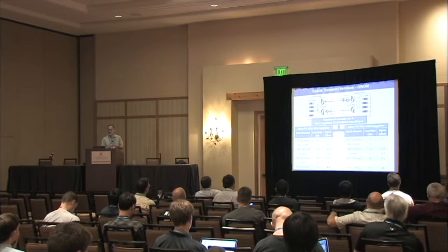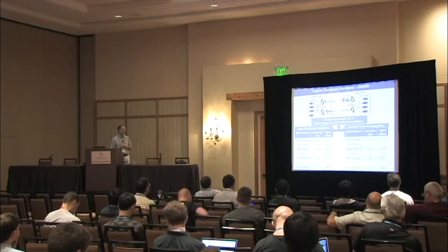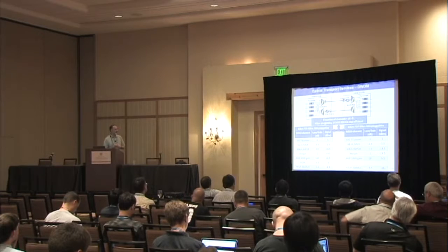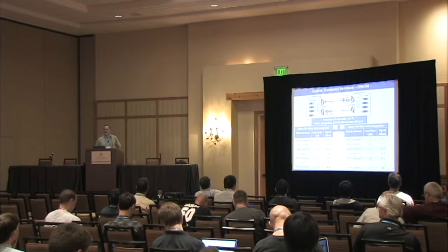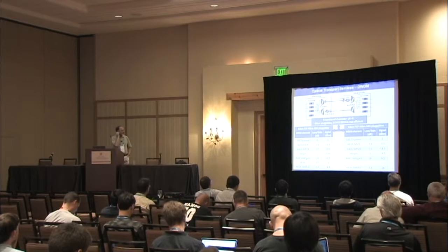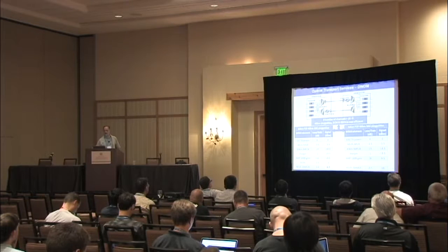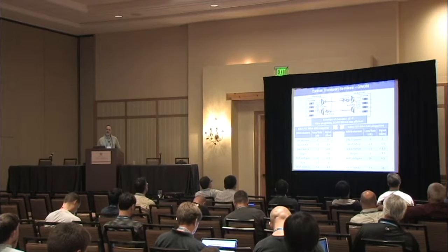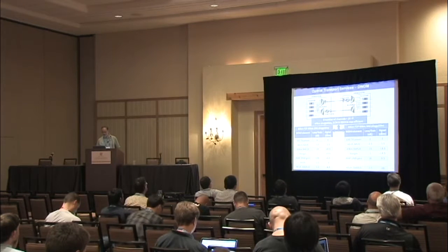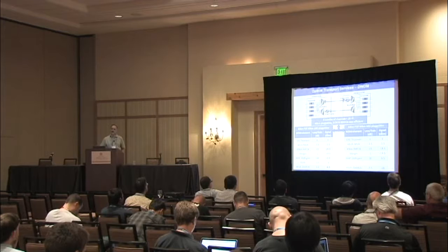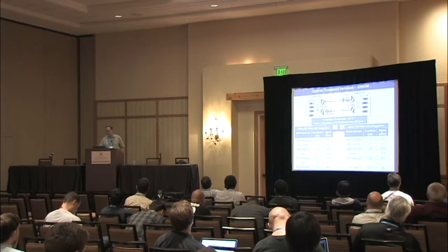My DCM that provides the dispersion compensation contributes an attenuation of minus 3.5, and the Dmax minus 6.5. I'm back within the active range of the transceiver. Now, looking at the 80 kilometer optics, it's exactly the same calculation. I can use a lower grade amplifier of just 10 dB because I have more sensitivity. I don't need a DCM because I have enough dispersion tolerance.